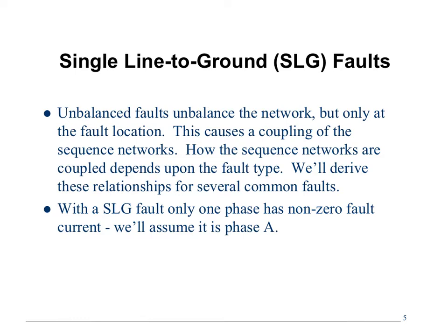So, what's one way to get the Thevenin equivalent voltages at each bus? It's your friend and mine. It's an NRLF, Newton-Raphson load flow, right? So if you actually have PSSE or PSLF, you can do a Newton-Raphson load flow. Most of the time, though, you actually do what's called a current injection.